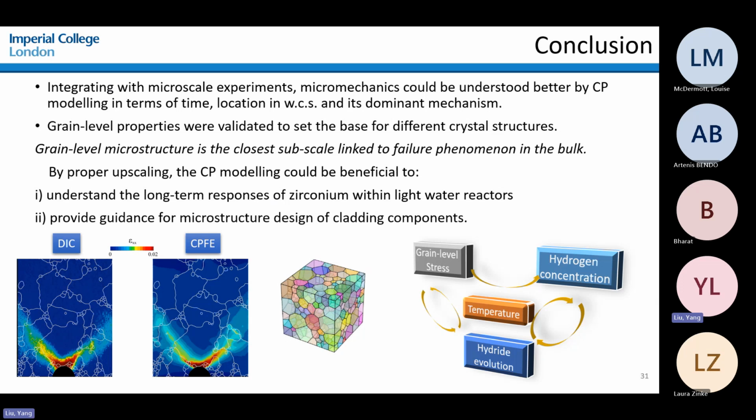Grain level properties could be validated to set the base for different crystal structures. And we have to emphasize here that grain level microstructure is the closest subscale linked to the failure mechanism in the bulk. So by proper upscaling of this microscale behavior, the crystal plasticity model would be beneficial to understand the long-term behavior of Zircaloy, and it will provide guidance for the microstructural design, especially in the new structural design within the small modular reactors, or in the new nuclear design.